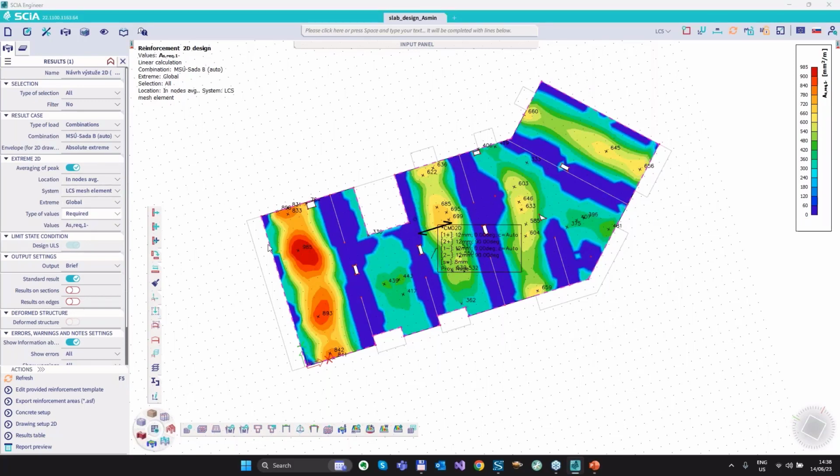And we can see the difference of application of minimum reinforcement if we select required static reinforcement, because it's without these detailing rules. So if I now display the results, you can see that the area of the reinforcement which is designed is smaller, because now we are focusing only on the reinforcement which is required by the ultimate limit state.